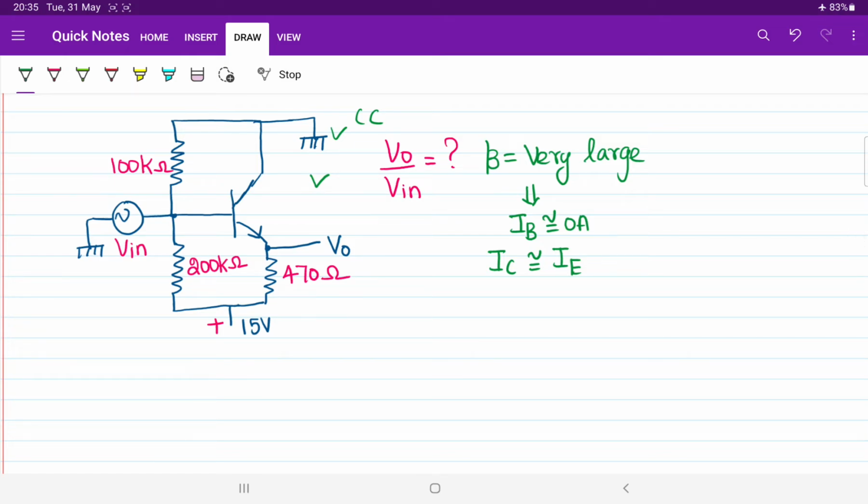If you observe the question carefully, it is an NPN transistor, and by observing the direction of the current we can guess. The supply voltage is given across the emitter terminal, whereas the collector is connected with the ground. It means that is called a common collector configuration. First, try to understand how to derive, whatever the procedure that I told you, just follow it. Now you may think, sir, whether the value of RE is required or not.